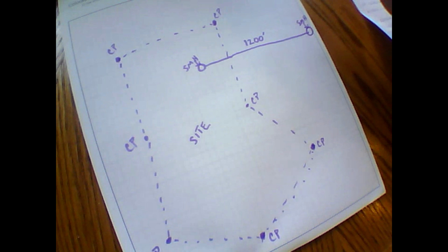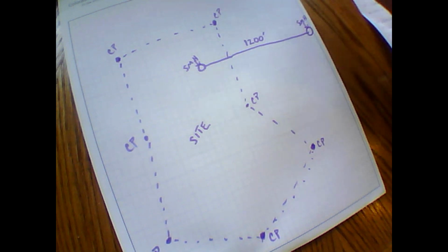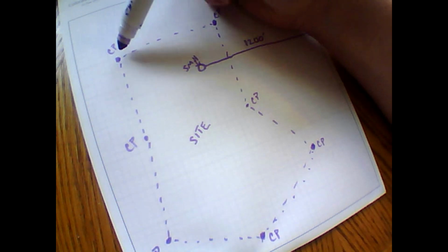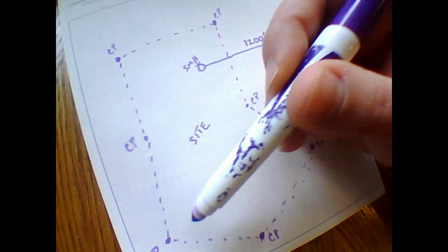You're not going to have a clue what system you're on. There's nothing to give you northings and eastings. That's what you want. You want your shot, your latitude and longitude, to equal this coordinate value, this northing and easting. Then you come over here, this northing and easting, same thing. Next shot, you want it to equal that. You're going to go around the site.